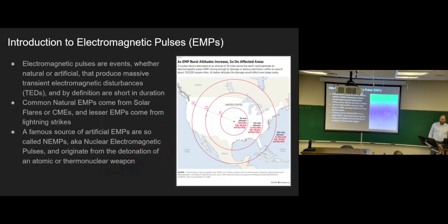All right. So, broad beginning. Electromagnetic pulses: at a high level, it doesn't even necessarily need to be a high amplitude, but at a minimum, it has to be an extremely fast change of the electromagnetic field. They're also known as transients. What you are familiar with, though, is ultra-high energy EMPs. The most common historical version of these is coronal mass ejections, solar flares. These are the types of things where large amounts of magnetic particles interact with our upper ionosphere and create massive fluctuations in Earth's magnetic field, which result in geomagnetic storms.